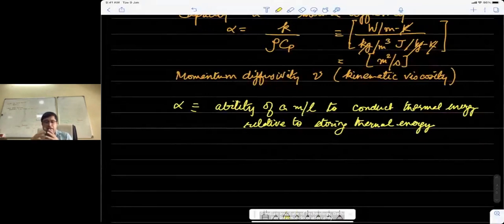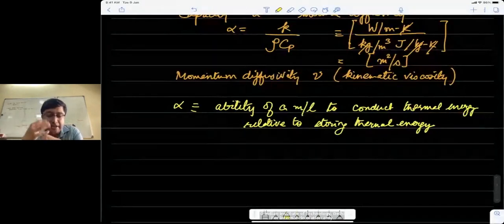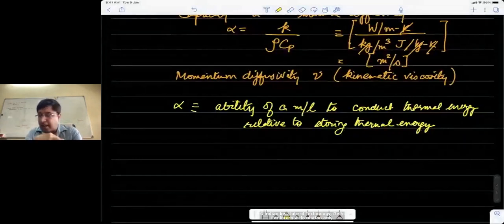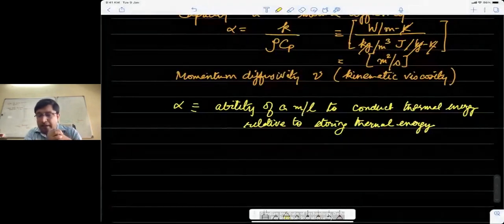And let's say that internally there is also some chemical reaction or some rate of heat generation. Maybe there's a current carrying conductor in the solid, or the solid itself is a current carrying conductor, because of which there is some ohmic heating. So given all these conditions, I ask you, can you calculate the rate at which temperature will change in this solid? So the energy conservation equation is the tool that we will use to predict how the temperature will change.